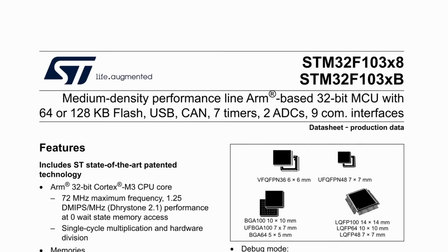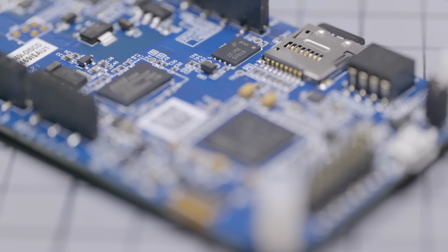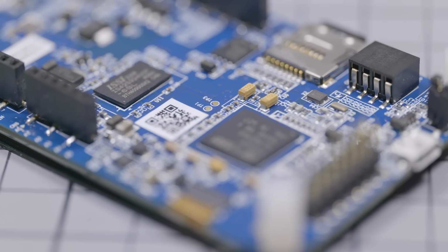The STM32 Blue Pill uses the STM32F103, which only has 20 kilobytes. Again, not enough. You need to get to a fairly powerful microcontroller, something like a mid-range Cortex M4 or so, to really get enough RAM to run this display without external memory. Speaking of that, if you're hoping to do anything complicated like double buffering or showing images, it's probably wise to add external RAM and flash, or find a development board that does that. If you're building your own hardware, you're going to need a circuit board to add that external RAM and flash to,